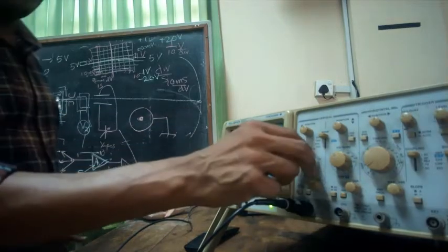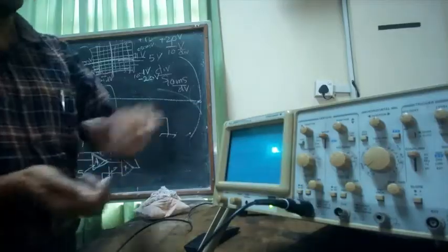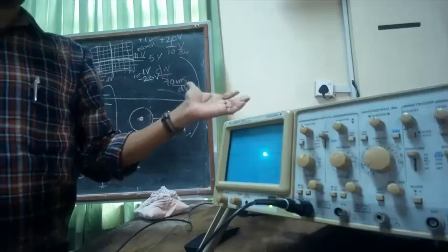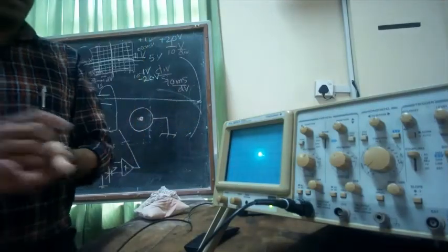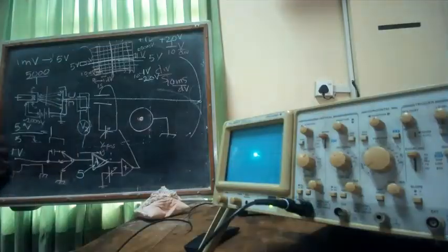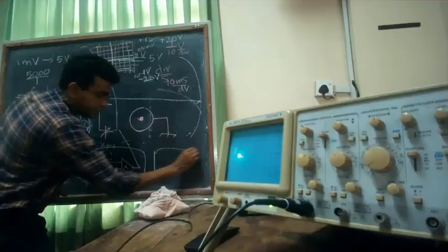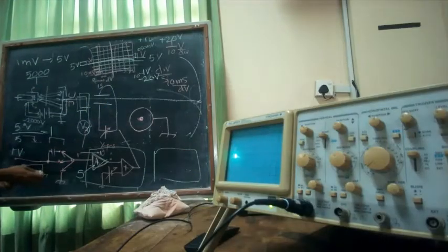So that's all this does. The purpose of the gain controller knob is that volts per division knob. That's all it does. Very simple. Okay, you understand now how it works, right? So there are two such channels, right? There is only one set of these, but there are two channels. So in order to allow that, I have to have two identical systems like that. There will be another set just like that, connected to another probe, and then you need to make sure which one is actually connected to the plates, right? Only one can be connected at a time.